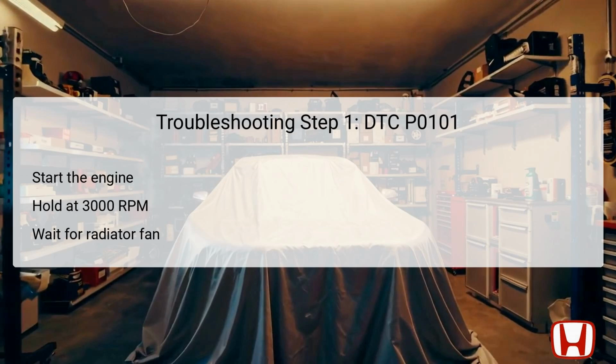It's essential to continue this for a specified time until the radiator fan actuates, as this indicates that the engine has reached operating temperature. This step checks the responsiveness of the system under controlled conditions, which can help identify if the MAF or MAP sensors are functioning correctly.